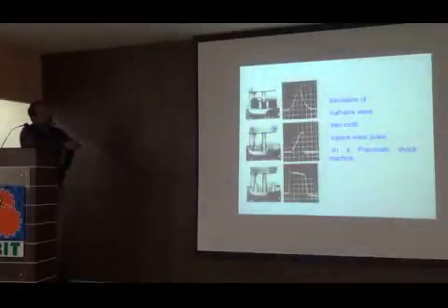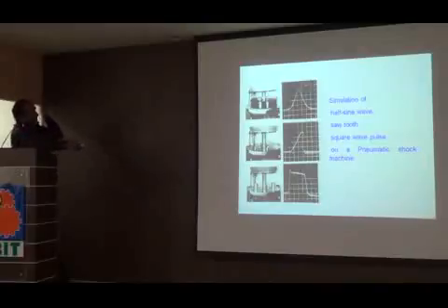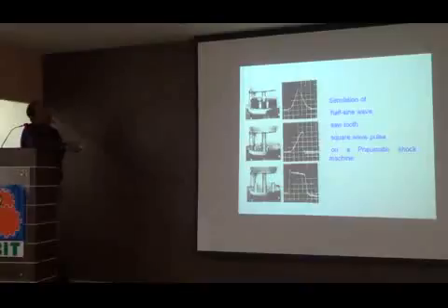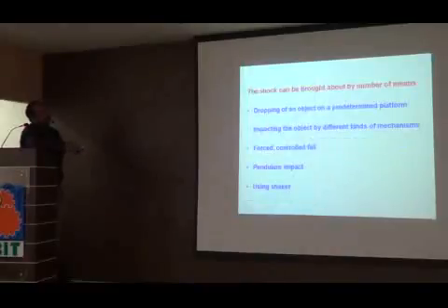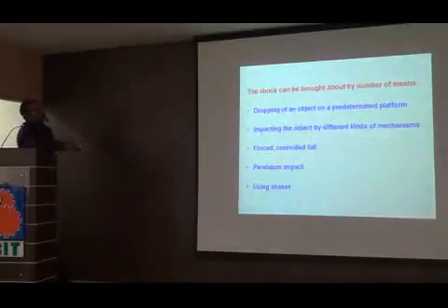How do we simulate this? If you want a half-sine, where the curve is like a half-sine, in the machine, between the impacting surface where the unit is going to impact, you need to have a rubber surface, or what we call elastomers. If it is a sawtooth, either a terminal sawtooth or initial peak sawtooth, you need some kind of lead pellets. If you want a square wave, you need to have some cylinders underneath the impacting surface to generate this kind of pulse. It can be produced by any other method also, either by impacting force or some kind of shaker.